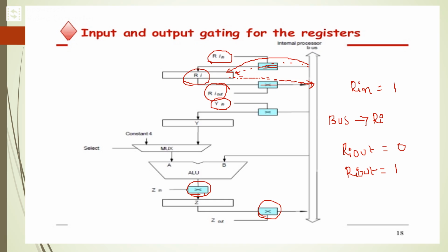If a signal being written is read at the same time, the final value is ambiguous. Hence, edge-triggered clocking methodology is used in all processors. When edge-triggered flip-flops are not used, two or more clock signals may be required for proper transfer of data. That is known as the multi-phase clocking concept.